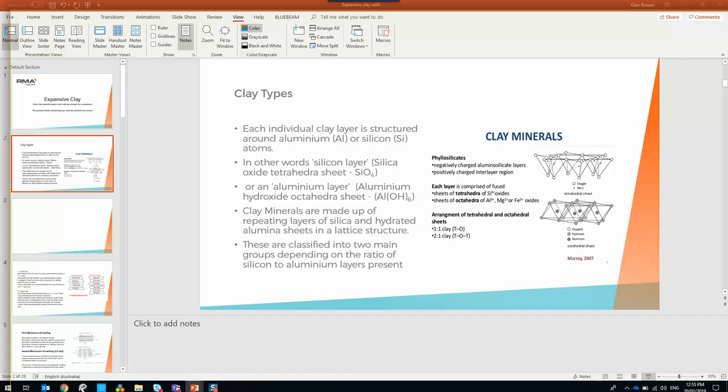I've even seen a job, we did the community hall out at Yarra Junction. They drilled the piers, I inspected them in the morning. We got about 20 mil of rain and it physically closed the top metre of the piers up and they had to re-drill them. So when you see that sort of stuff, you just understand what you're dealing with and how to avoid it.